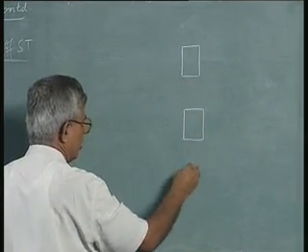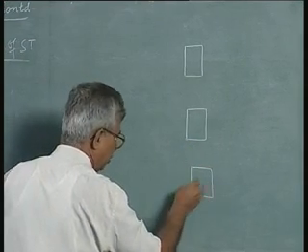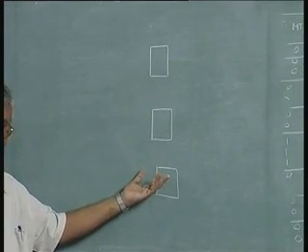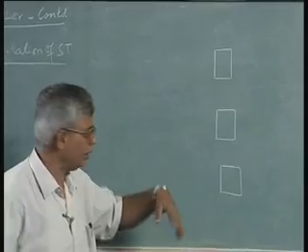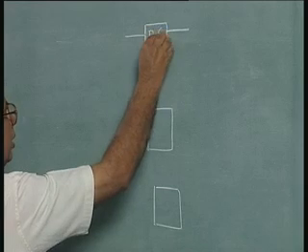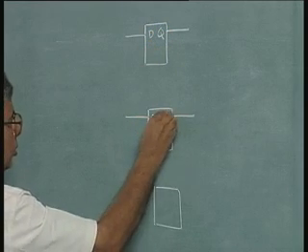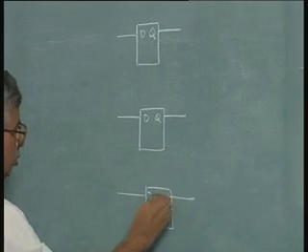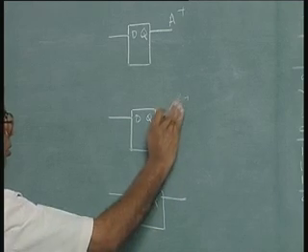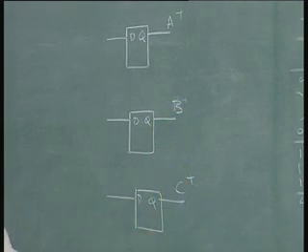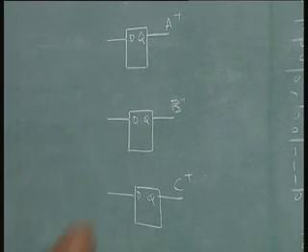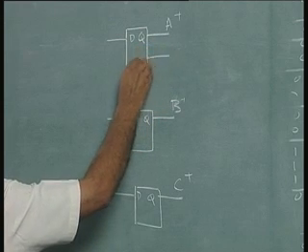I think this is something which we already described in detail in the previous state graph technique as well as the ASM technique using multiplexers. Each variable will have a flip flop, a D flip flop, Q is connected. So this will be my A plus, if you want to call it that. Actually A or A plus is the same, because the next state becomes the present state, and then the complement of that.